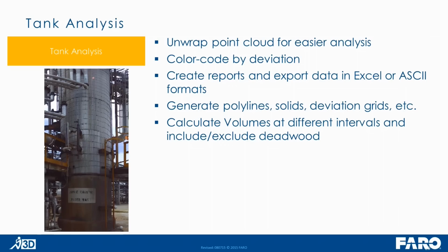I also wanted to talk about planar analysis as well, but this tool and the planar analysis actually got covered in some of the other presentations or in the previous presentation. But that tool, as it pertains to tanks, is very nice because you can unwrap the point cloud like you saw earlier. You can also create very detailed reports in Excel, and then you can create that polyline grid that we saw in Christina's presentation.